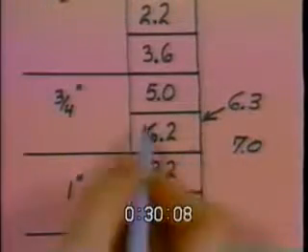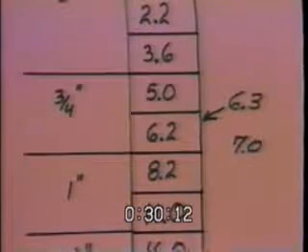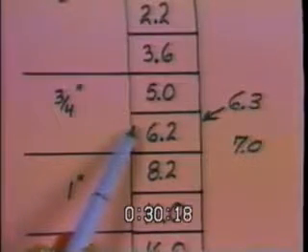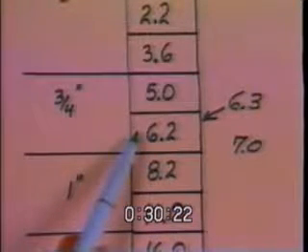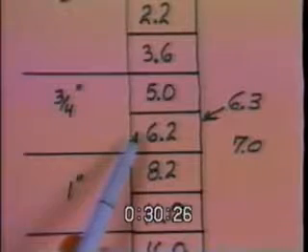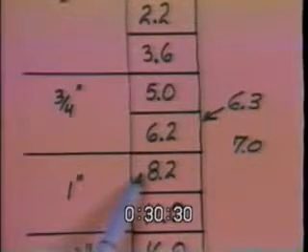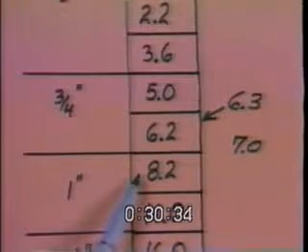Now that falls right between these two categories. Which one do you pick? That's a choice really up to you. If you choose the smaller one, you'll have much better control. But you run the risk of insufficient heating or cooling at design conditions. In other words, 10 days in January perhaps. If you choose the higher CV, you are oversizing a little bit. Therefore, you're not going to have as good control.